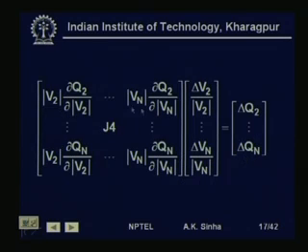And the other set of equations uses the submatrix L, because we have multiplied del V by V. So, here we have delta V2 by V2 to delta Vn by Vn, and this is delta Q. This is the other set of equations that we need to solve.